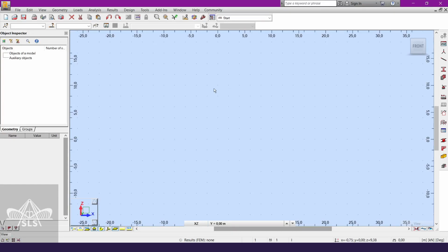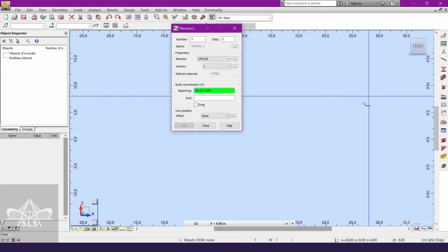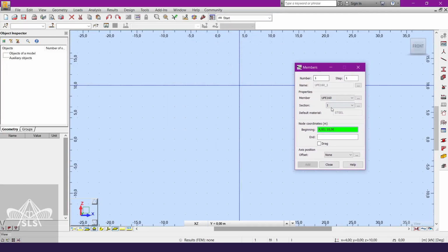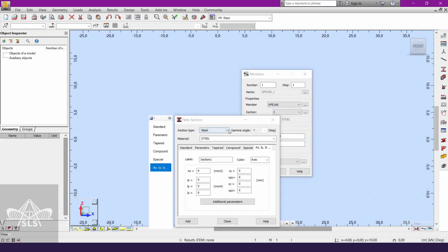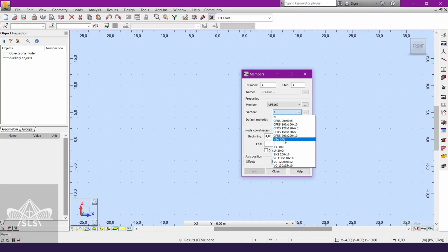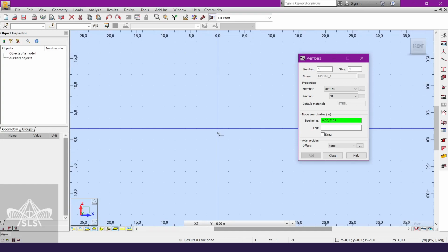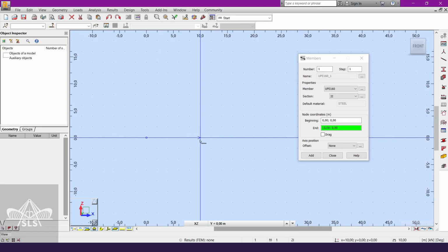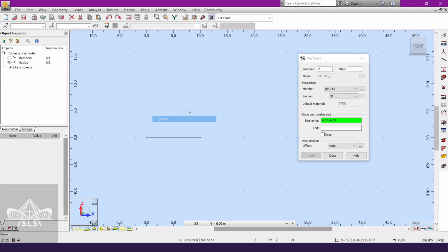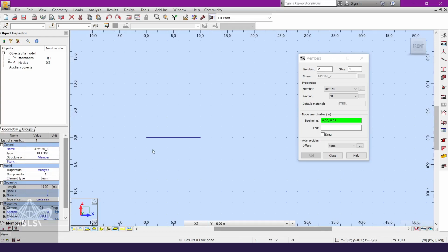If we need to start modeling, the first thing to be done, we can just select and start to create a simple member. As you can see here, I already defined the section I, for example. Here we have the I section, we have the 2I section, and now we can continue to select the 2I section because the first span from 0 to 10 meters in this case is going to be with this value as shown from the task. Next we select the node and then we go at 10 meters, and now we already have our member with moment of inertia 2 times I.